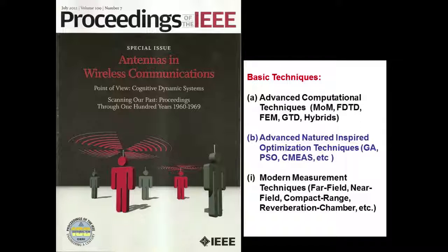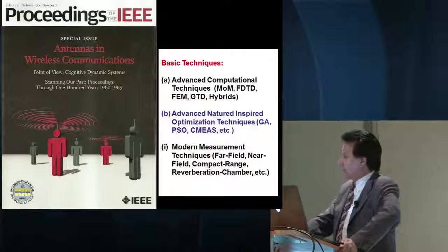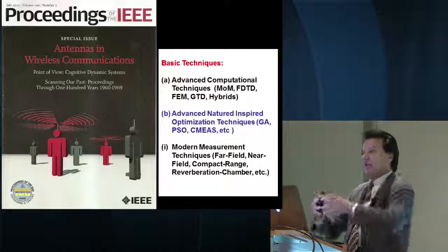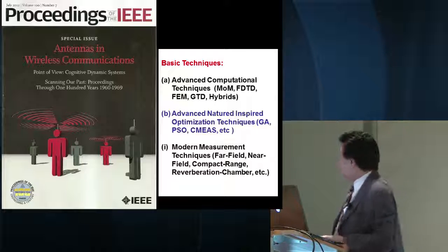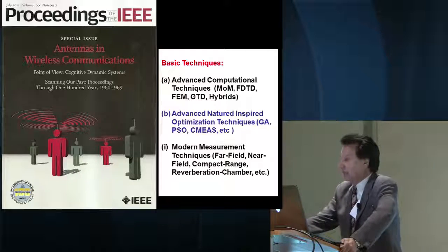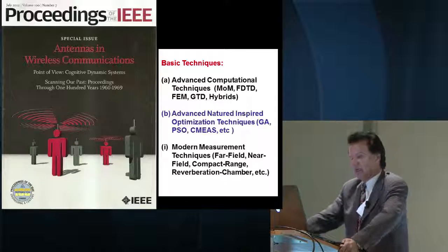If you walk through these proceedings, you see several topics, and I touch upon some of them here and there. One is the basic techniques. We have very much advanced how to work with Maxwell's equation, and that has brought us advanced computational techniques, like method of moments, finite difference time domain, finite element method, geometrical theory of diffraction, and hybridization of these techniques. That allows us to do very detailed design on the computer. Along with that, we have also evolved advanced nature-inspired optimization techniques like genetic algorithm, particle swarm optimization, and so on.